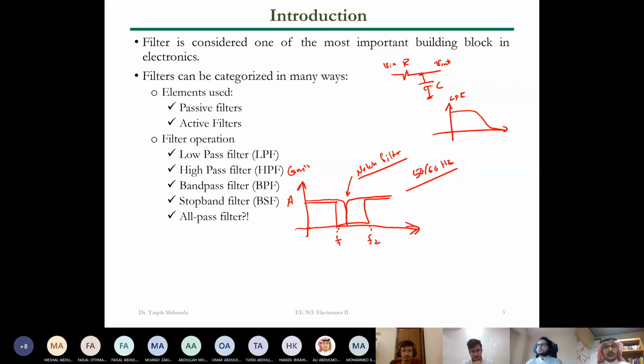In the frequency response, we said, okay guys, when you test the behavior of the system, whether it is low pass, high pass, and so on, you may just use the zero frequency and the high or infinite frequency, where f equals 0 and f equals infinity. And then you can draw the circuit. This is a sketch to give you the pattern here. Right, this is a passive filter.